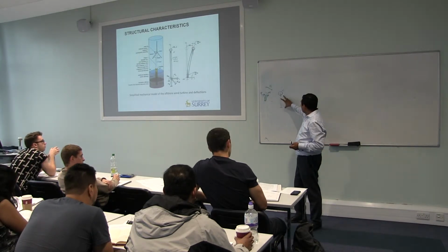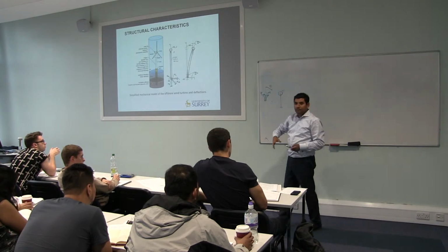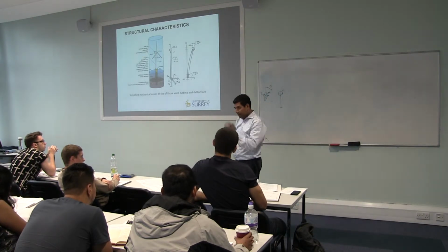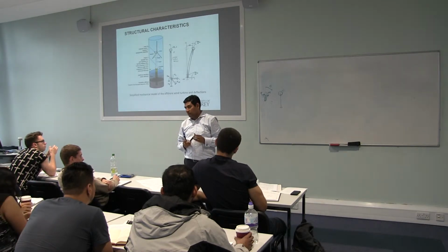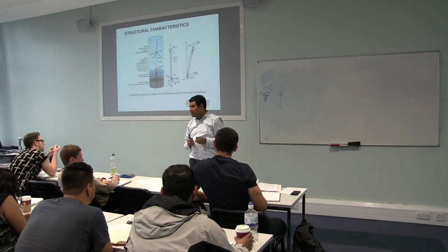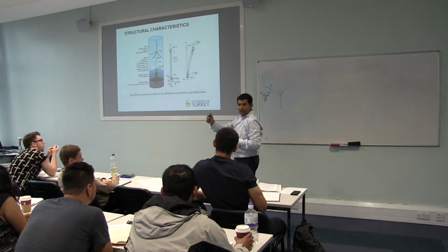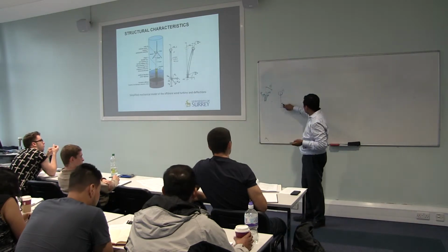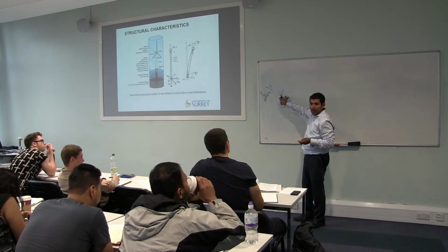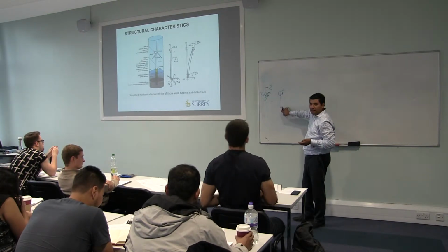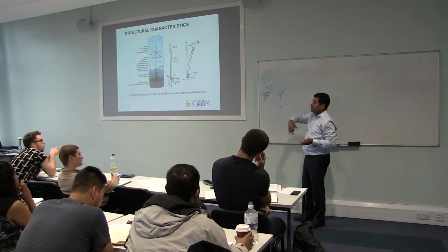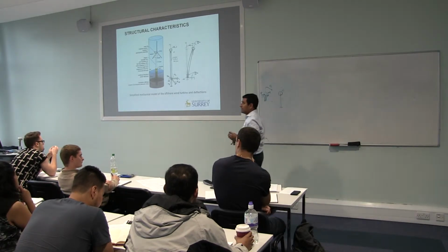Basically what you do, you set up the whole geometry, and you find out the eigen solutions of the problem. Those who have done some dynamics can easily recognize that. Once you set the whole problem up, you give the pile head mass, you give the top mass, and the stiffness to the springs, you find out the eigen solutions.